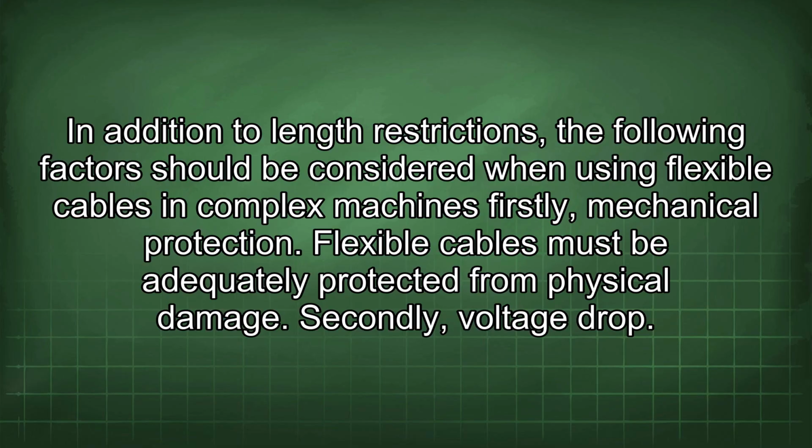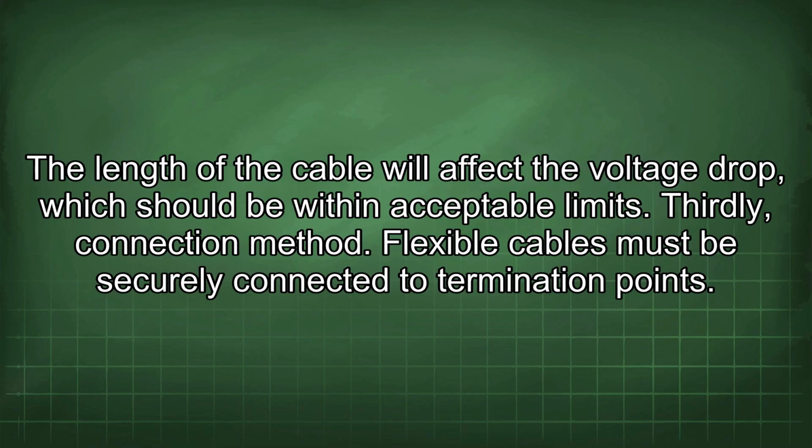Firstly, mechanical protection. Flexible cables must be adequately protected from physical damage. Secondly, voltage drop. The length of the cable will affect the voltage drop, which should be within acceptable limits. Thirdly, connection method. Flexible cables must be securely connected to termination points.